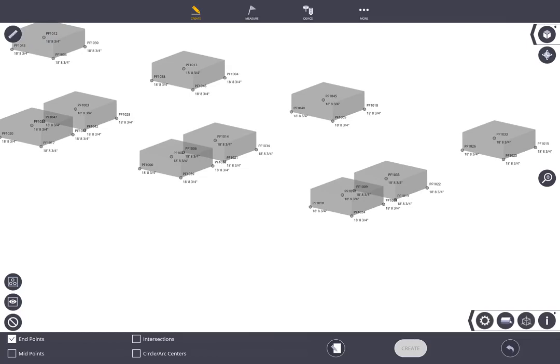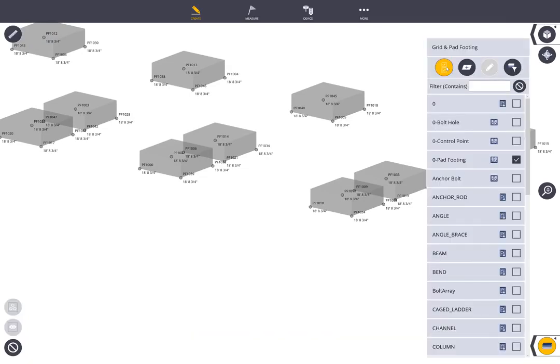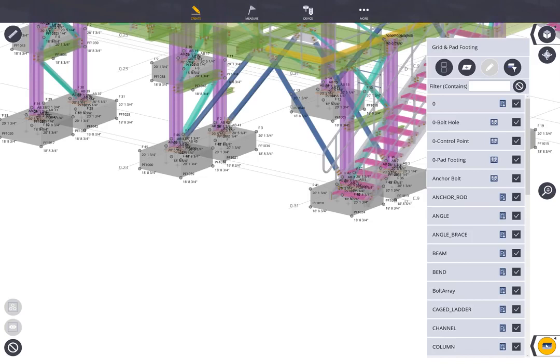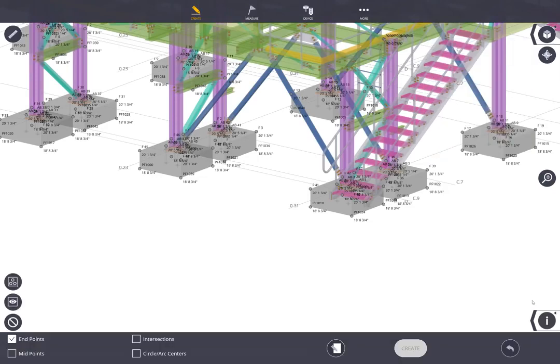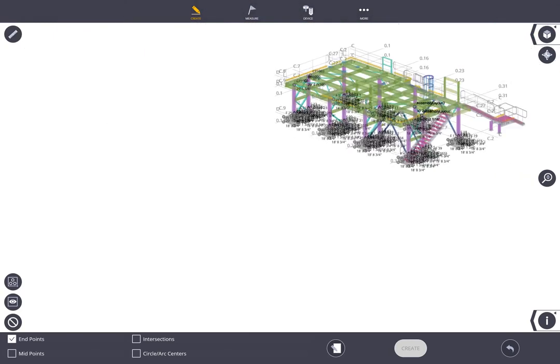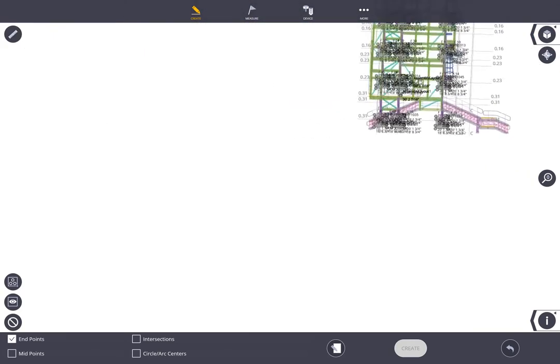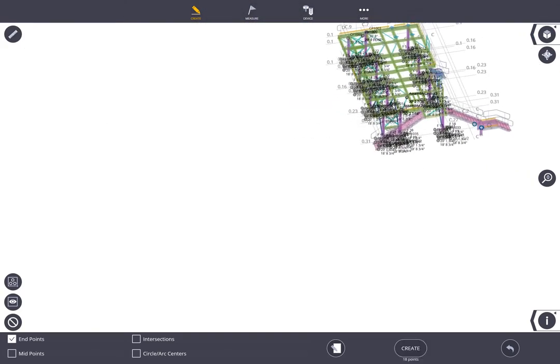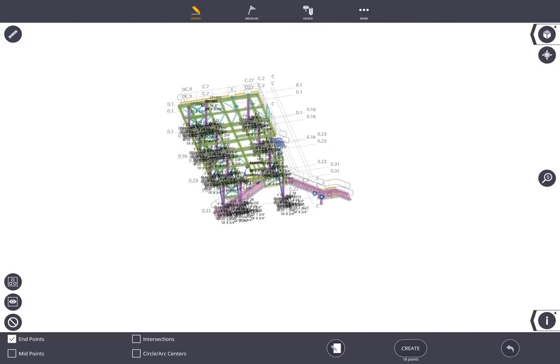So we'll go ahead and turn the rest of the layers back on and close the layer tool. We also have an undo button just in case you do something you don't want to complete. We can actually hit the undo button and undo the last action that you just completed in that menu. All right, so now if we wanted to isolate a certain section for prefabrication or whatever you want to do here, I can go ahead and drag that into an isometric view, put it back into 2D format, and I'm going to lock it down here.